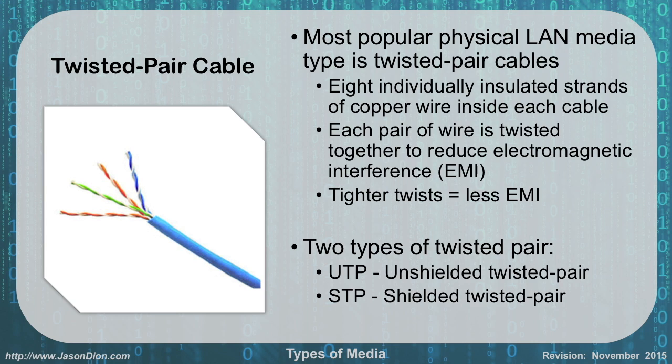One of the things you're going to notice if you ever take apart one of these cables, if you take an old Cat3 cable, the twists are very far apart. Maybe say 1 twist per inch. When you go to a Cat5, there's more twists, maybe 3 twists per inch. You go to a Cat6, it may be more twists, like 8 twists per inch. And so the more twisting you have, the less EMI, the faster data speeds and the further it'll go without interference.